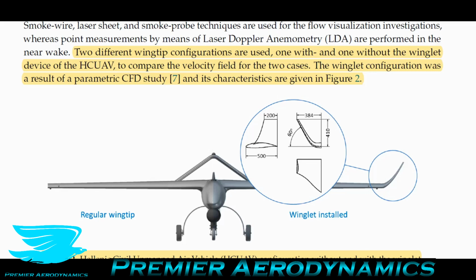The winglet is tilted up at an angle of 60 degrees, and it tapers towards the end of it, which is typical of a winglet. And it also has a profile as well. It seems like it keeps this NLF 1015 profile as you go up.